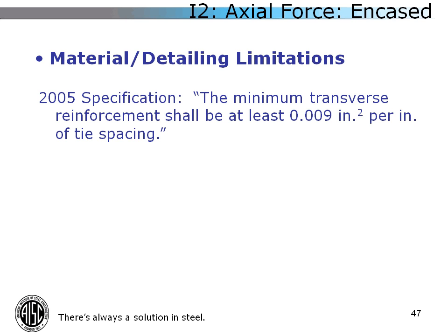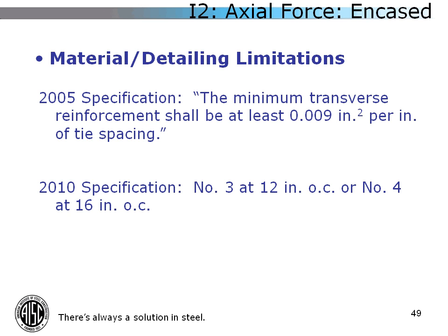So guess what the 2010 specification says? Use a number 3 bar at 12 inches. All right? You can tell that there are actually some design engineers on the committee now. So we tried to clarify some things.